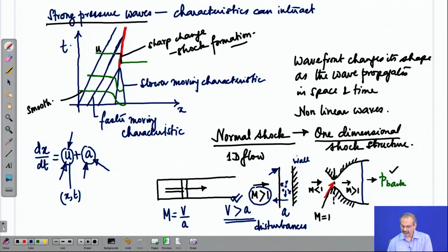And because of the geometric nature of the wall, the shock has a flat structure, which we are calling as a normal shock. In this situation too, the moving surface which is creating the compression is flat in nature, and therefore, the high pressure front which finally forms a shock wave ahead of it also has a flat nature, which is again a normal shock.